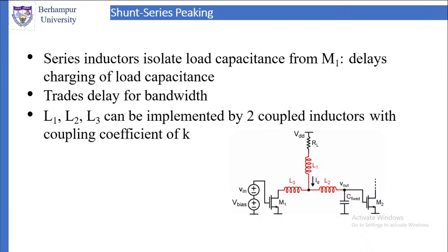because of L, the charging of the capacitance will be delayed, because L itself will have a time constant, L by R. For capacitance, the time constant is RC. When you have inductance, the time constant is L by R. So that way there will be a delay, and that delay will delay the charging of the load capacitance.